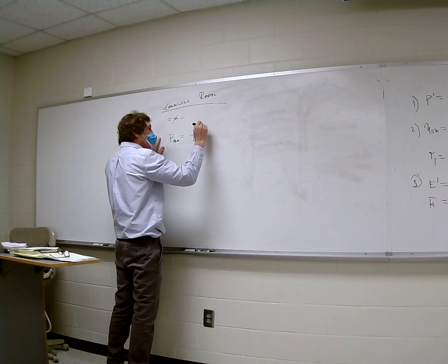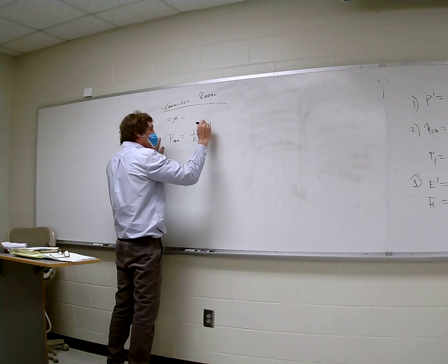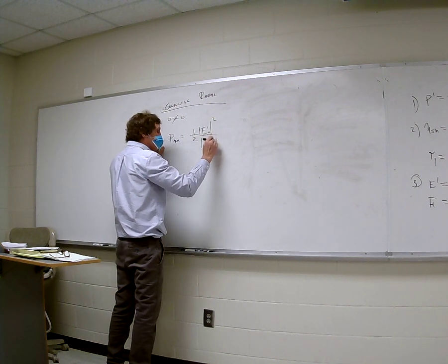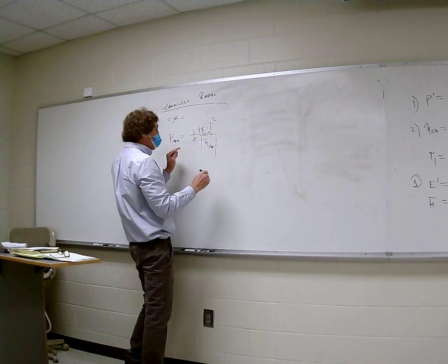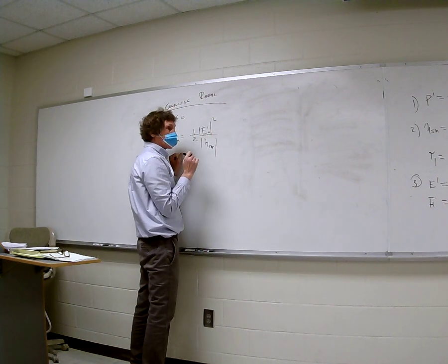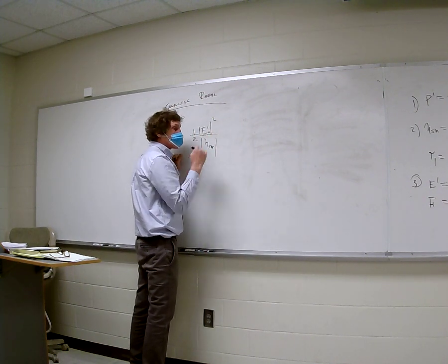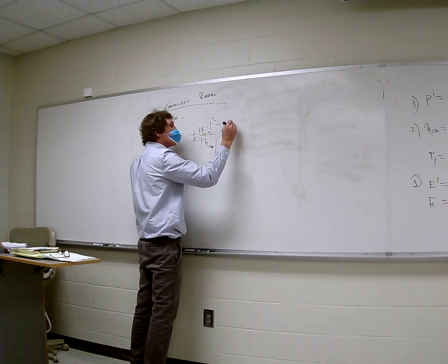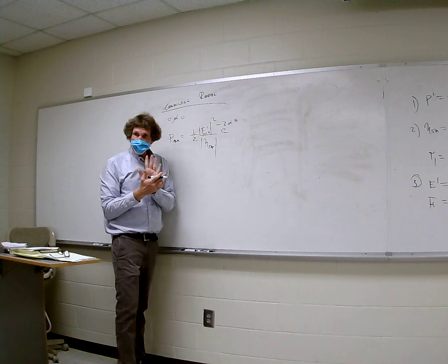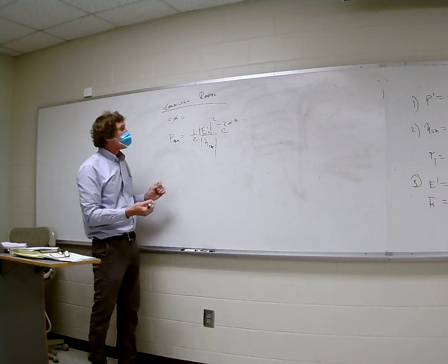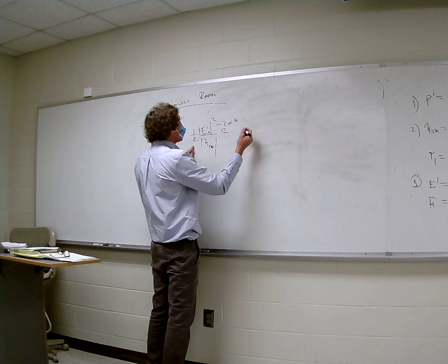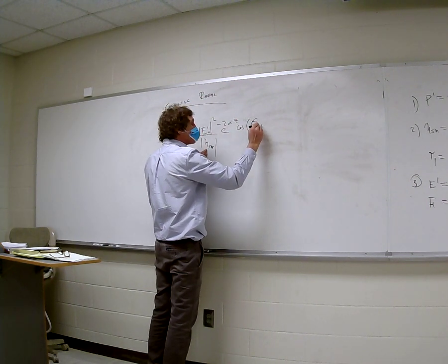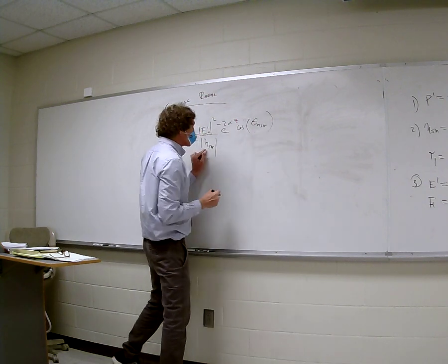magnitude of the E field propagating through that region divided by magnitude of the intrinsic impedance in the region. I'm going to call it eta S. Now, if there is something where they want to calculate power intensity, like at the middle of the shield, then it will be e to the minus 2 alpha times z, where z would be the depth into the shield. Are you with me on this? And then it's going to be times the cosine of the angle associated with the shield impedance.